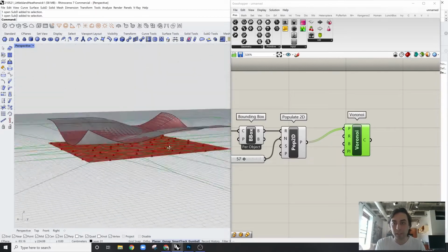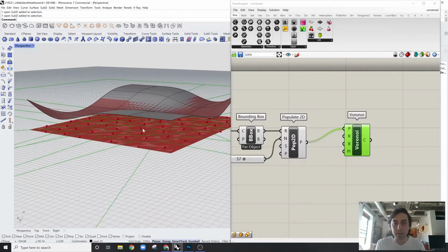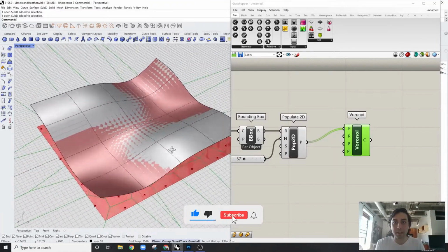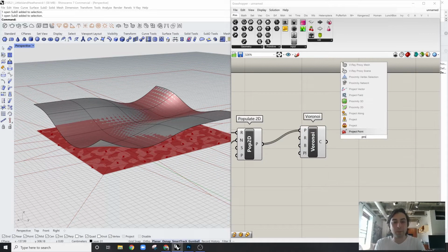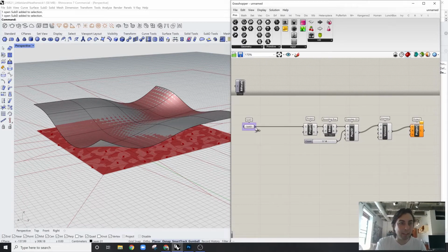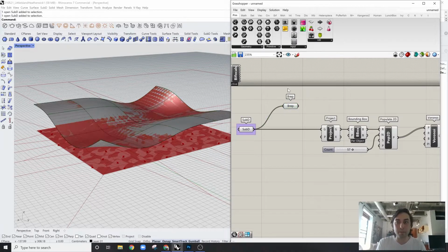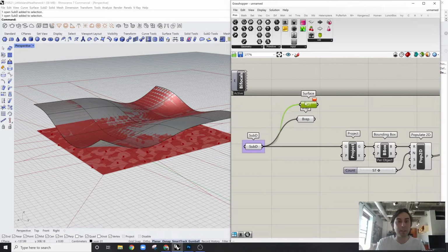Now it's going to give us the planar, which we can see how that's going to relate. So now what's going to input is a bunch of polylines here. And so now we can just project those polylines, project a curve onto a B-rep, perfect. And we're going to bring back in this, because sub D and B-rep can be interchangeable. This is an interesting part. Sub D and B-rep can be interchangeable, but sub D and surface cannot be interchangeable. So that's not going to work.